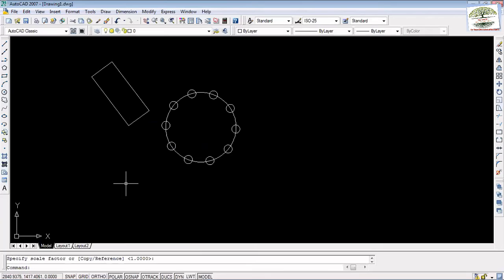Clicked, done, scale changed. If you'd like to go for SCALE again, space, I'm selecting it and right clicking on it. I have to select the base point. That's what I showed you with the manual selection. If you're scrolling the mouse, you can change the size of the object. So you're changing the scale.